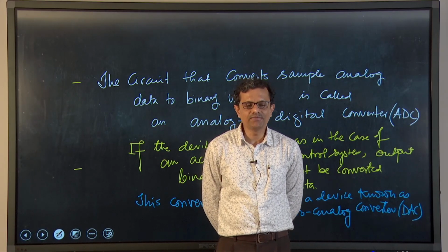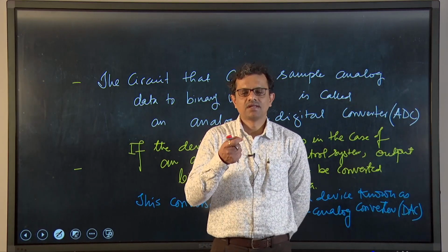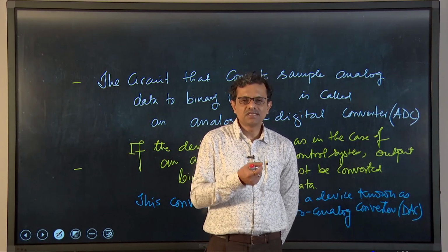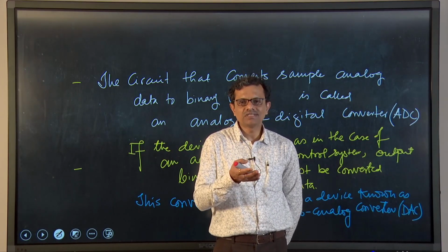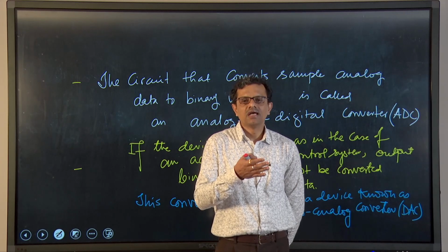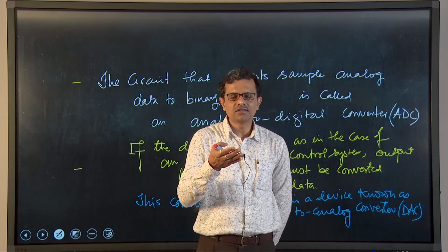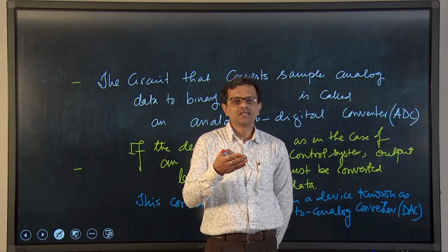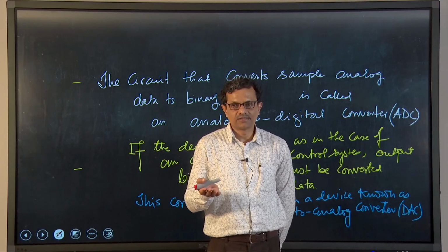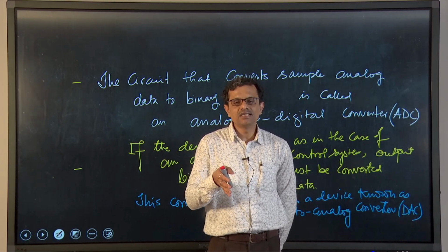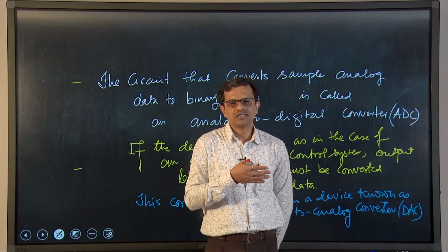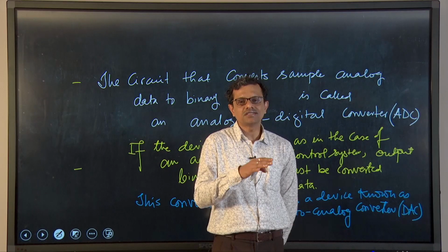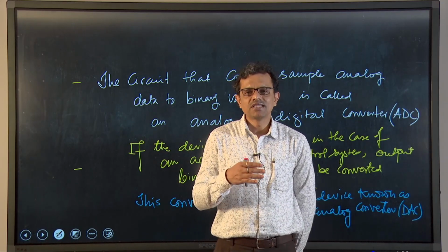So, if we need to have a very sensitive ECU, that means receiving signal from the sensor, ECU will do some calculation, ECU will perform some task and give some information to the actuator to correct the problem, and will give some information to the actuator to take a decision on what to do next. So, all these things are done using the ECU in modern engines, and the functionality or the efficiency of this particular unit depends on the solid state